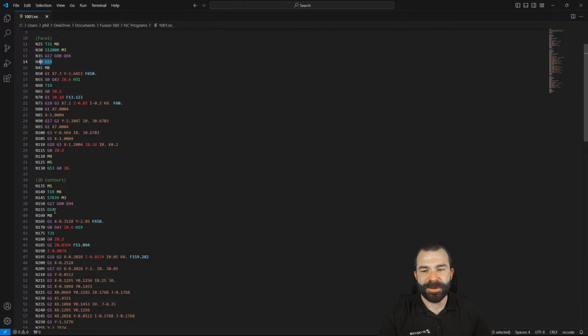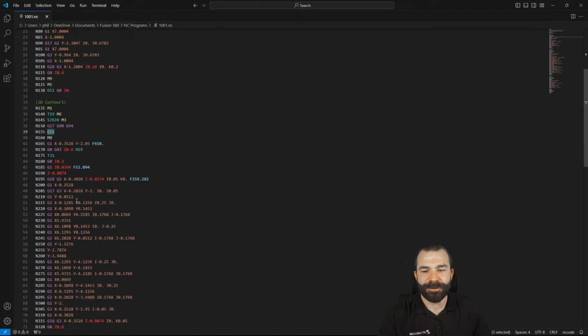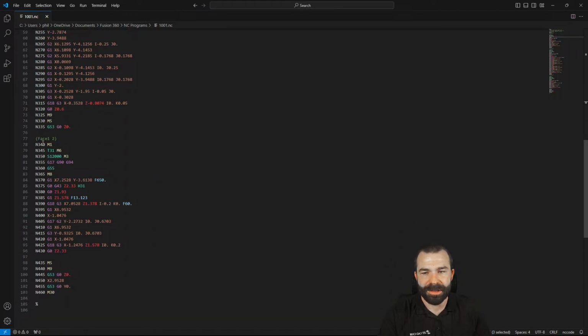Again, first setup 54, then contours 54, and then when we roll down here into our next face, you're actually going to notice that we have that 55, right? So now we've done 2 setups on 2 separate work offsets. Again, run 2 vices in your machine. Maybe you got to make 50 parts.